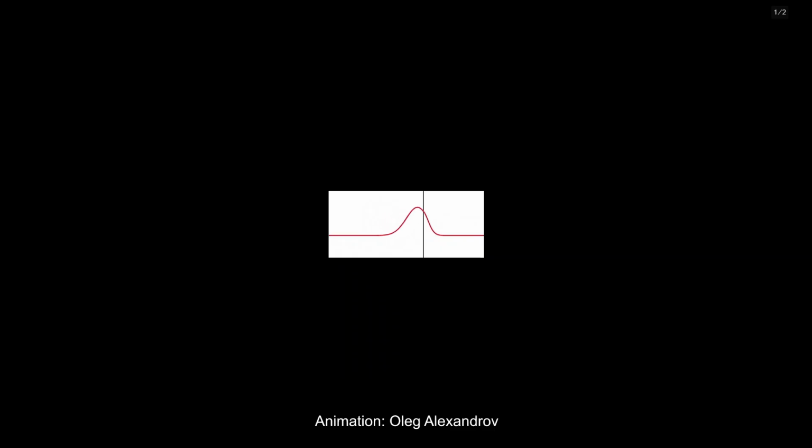A similar thing happens to electromagnetic waves traveling between conductors. When they see a discontinuity, for example, a change in impedance, like the case when a signal goes from a PCB trace to a load resistor or to a digital logic input, part of that energy is reflected, and the remaining part goes through the load.